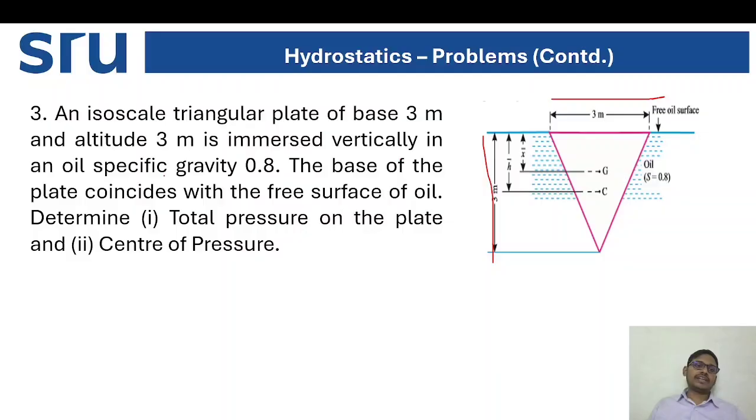Is immersed vertically in an oil of specific gravity of 0.8. The base of the plate coincides with the free surface of oil. Determine total pressure on the plate and center of pressure. So both ways we have to calculate. One is total pressure on the plate and second one is center of pressure.